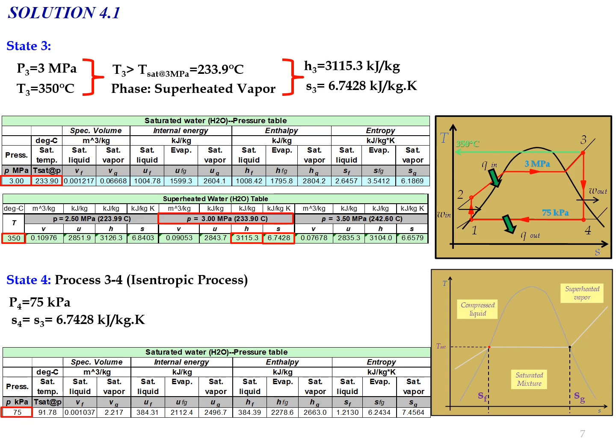At a pressure of 75 kilopascal, we need to find the value of SF and also SG. SF represents the entropy at the saturated liquid condition, and SG is the entropy at the saturated vapor condition, as shown in the TS diagram, which are the lower limit and the upper limit of the saturated mixture region.